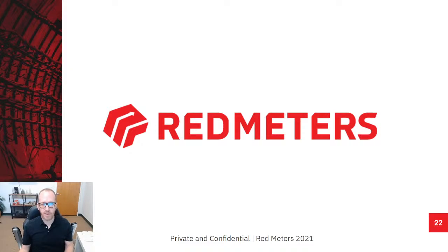So they can calibrate them within our software. Our software has a calibration module for external devices. You just set a high and a low, and it interpolates between those two. So yeah, you could just have a pressure and a flow meter connected. The red meter, however, makes a unique calculation for density, so other density measurement devices are not going to translate.